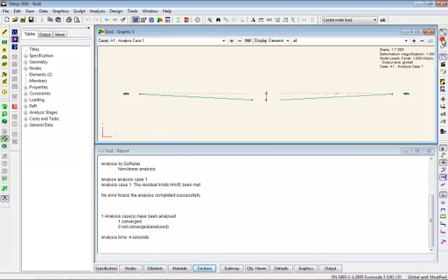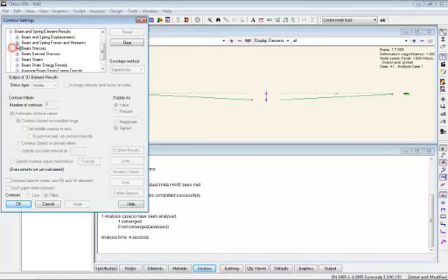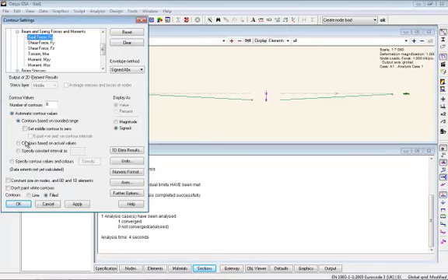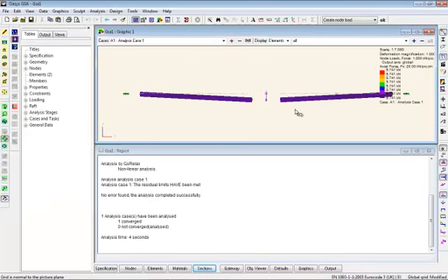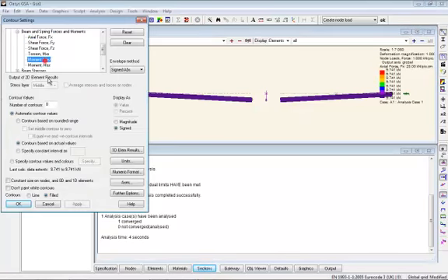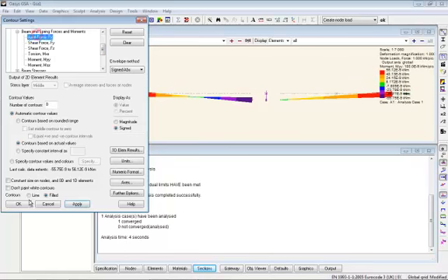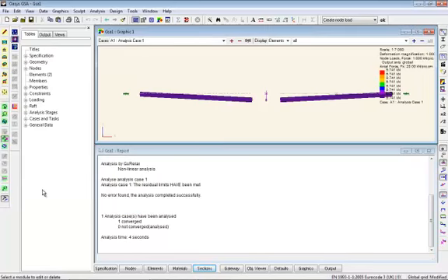And unlike previously where we had bending moments, this is being taken entirely in axial load. There may be tiny moments on there, but they are sort of rounding errors really, rather than the real thing. Essentially this is now an axial load model.